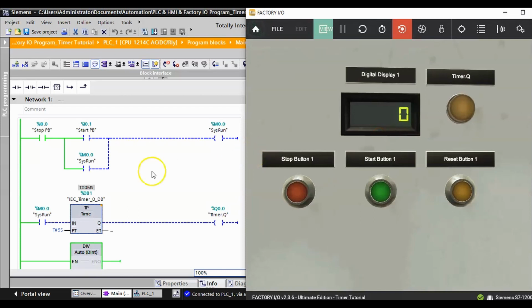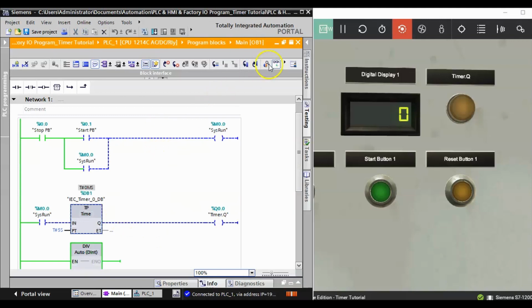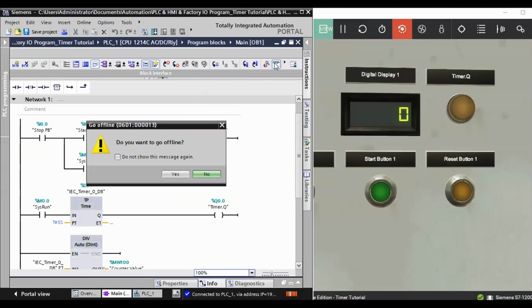So this is where you have just one pulse come through, and you need to kind of make use of an off delay timer here. So pulse comes in, pulse is gone, keeps incrementing up until the two values are the same, and then the timer output turns off. Most of the time you'll be using an on delay or an off delay. This is a cool little timer, a pulse timer, that you can make use of as well.